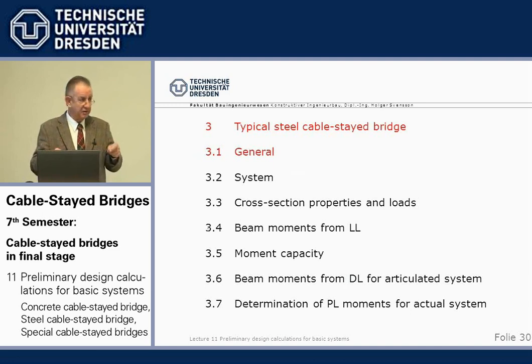And of course we had the normal forces for these, and we can combine them, we can calculate the stresses. We can, for the bridge beam in the center, superimpose post-tensioning, just the compression force, by, for example, the condition no tension at the bottom and within the permissible range of compression in the top.